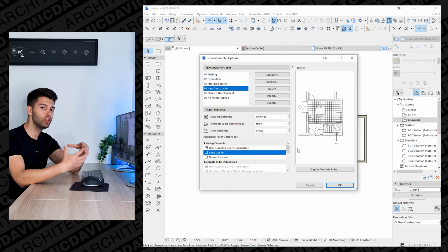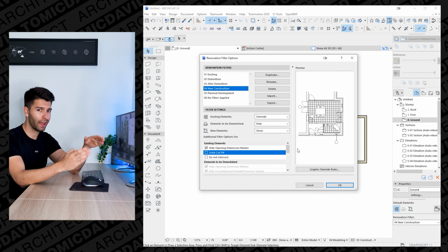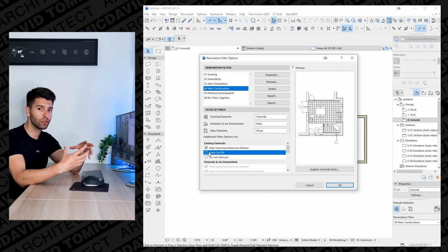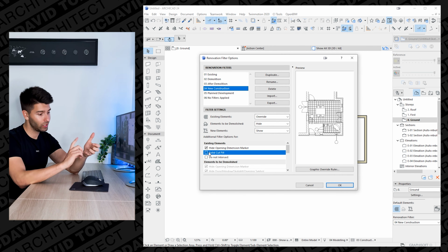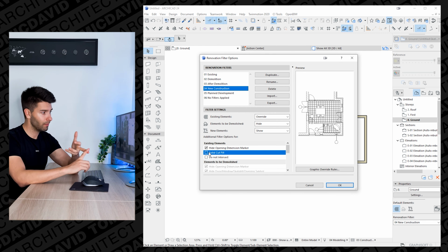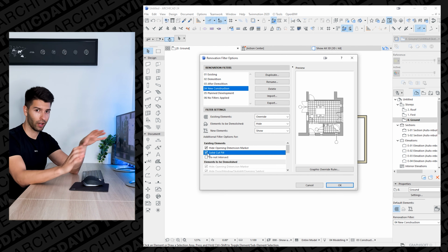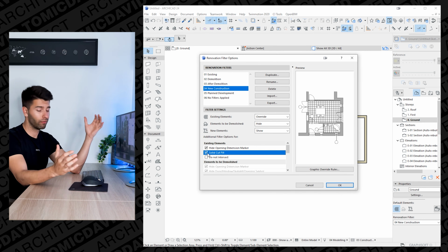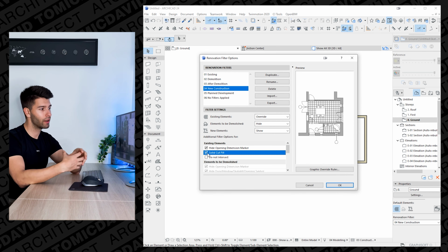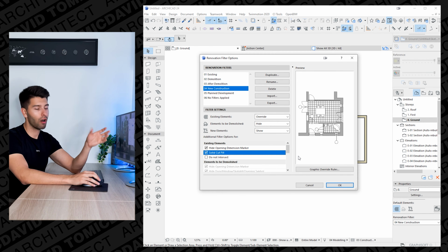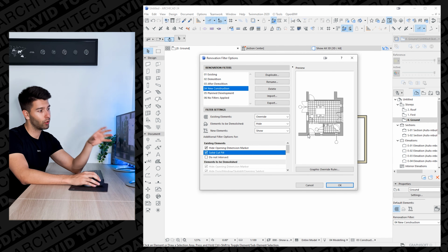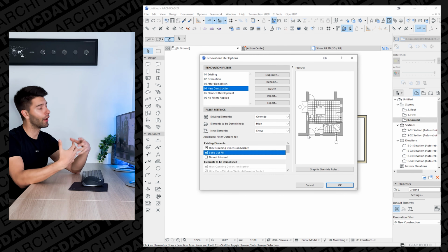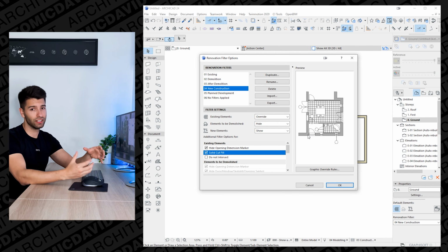And if we wanted to continue that theme, showing all those walls as gray or potentially white or whatever we had in mind, and we didn't want to show that as just a textured wall because we didn't know what was inside. We didn't know if it was brick, if it was concrete, if it was timber. We could simply just click that box and hide it all. So in an instance where you weren't entirely sure what that material was made out of, or if it was a 500, 600 deep wall that you had no way of accessing internally, you could hide all the materiality and all the internal information of a wall on a construction drawing simply by clicking one layer and not having to go in and do an abundance of 2D work.